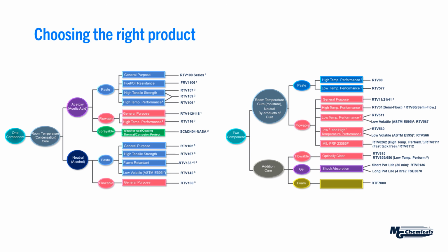Do we want high tensile strength? Do we want something that's low outgassing? Do we want something with some oil resistance? So it's not so much the products that I'm highlighting here. It's the stepwise asking questions, gathering requirements in order to arrive at, usually you can get it down to about 1 or 2 different materials to recommend based on these different requirements that come in.